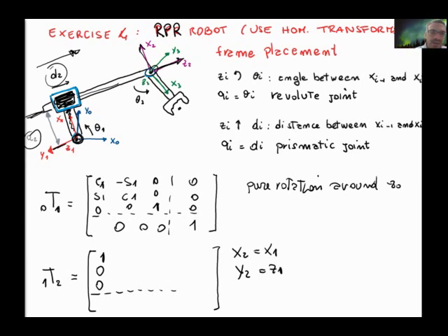And finally, I look at the Z2 axis and I see that it is opposite to Y1. So to build the rotation matrix, I look at the Y2 axis and say this is like the Z1 axis. So I put one for its projection along the Z1 axis and 0 for the others, while for the Z2 axis, which is the third column, I project along the Y axis with a minus, and I have zeros here.